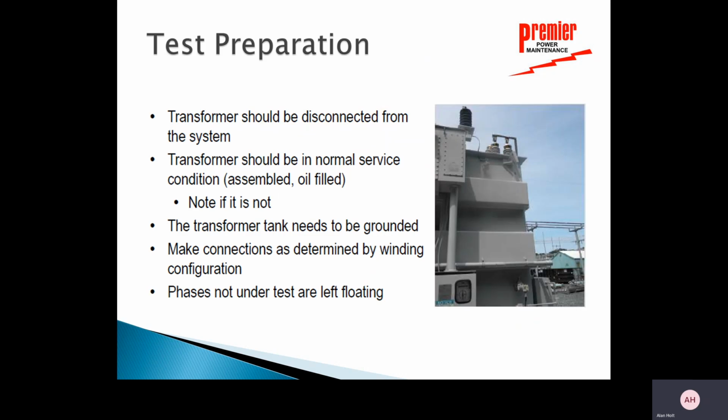So let's talk a little bit about test preparation. So obviously the transformer's got to be disconnected from the system, okay? Transformer should be in normal service condition. I want it to be assembled and oil filled, because that's what I want to use for my historical data. If it's not oil filled, make a note of it, because it's not comparable to historical data.